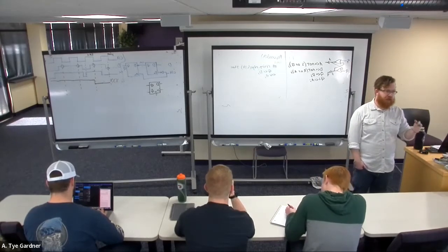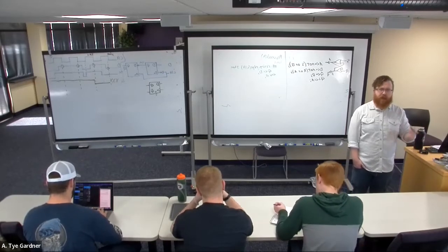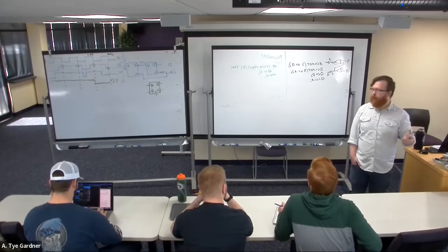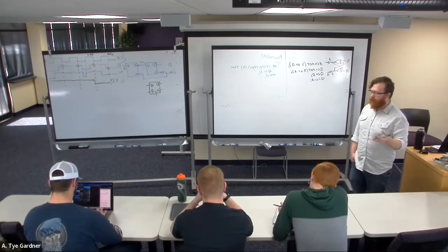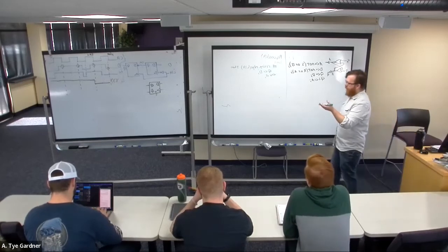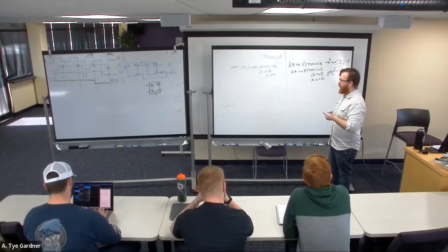Synchronous means that the reset must be active on the rising edge of the clock. Asynchronous says that it will react whether or not there's a rising edge of the clock, meaning that the reset is kind of more important. The reset is the most important thing, is basically what that means.